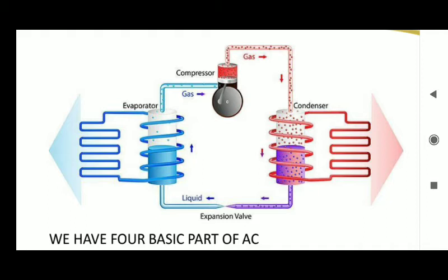The same thing happens within a compressor. When you energize it, it compresses the refrigerant to the extent that the liquid begins to boil. And as it's boiling, the pressure increases. And check the direction of the arrow. As the arrow goes, the first place it goes after the compressor is the condenser coil. And the condenser is always installed outdoors. And what happens at the condenser? The condenser is a heat exchanger. It ejects the excessive heat generated by the compressor outward.